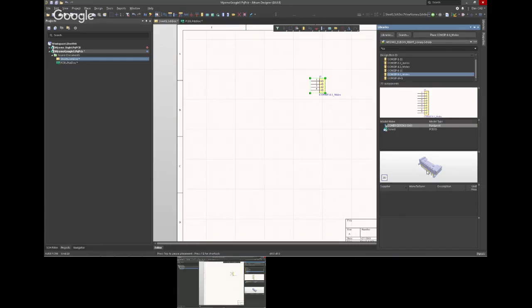But the beauty of it is that it actually helps reduce your file size. We know how big a file can get with embedding step files. They tend to get very large as I start embedding a lot of step. But now, since you're dealing with native solid part, having the connector, it reduces that file size and you don't have to deal with large parts, and actually enhances that when we push it back over to the mechanical team because it deals with native solid model.